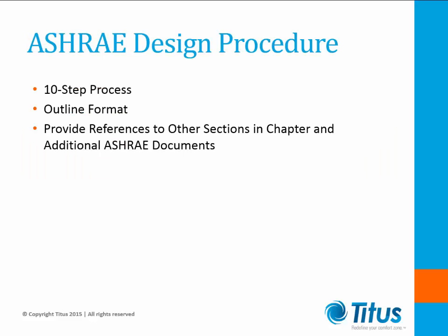ASHRAE's duct design procedure. ASHRAE provides a guideline procedure for duct design in Chapter 21 of the 2013 Fundamentals. It is a 10-step process in outline format and provides additional references to other sections inside the chapter, as well as other ASHRAE documents. It is a great reference as a starting point and can be used as a checklist.